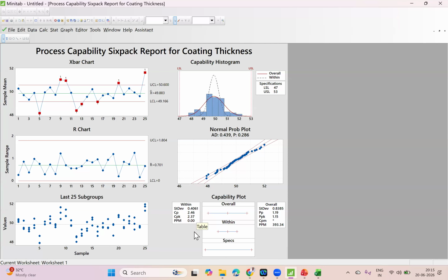Yes. But the same process, if you use it for a long-term application when your customer wants a continuous supply, every day 5,000 pieces, non-stop. And now, in addition to CP/CPK, you need to think in terms of PP/PPK also, because your requirement has now become long term. So what is this PP/PPK? How to do the calculation? And luckily, you don't have to study separately. With the same data, you can calculate PP/PPK. I'll tell you that a little later when we come to the same topic one more time.